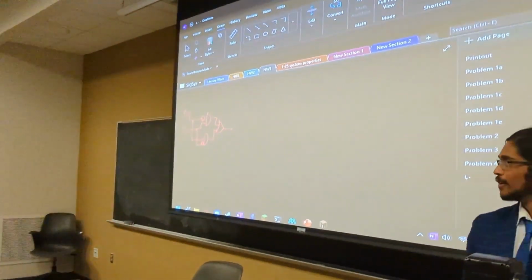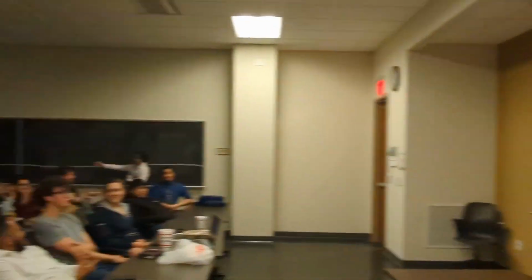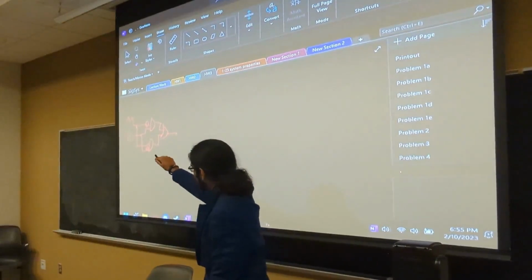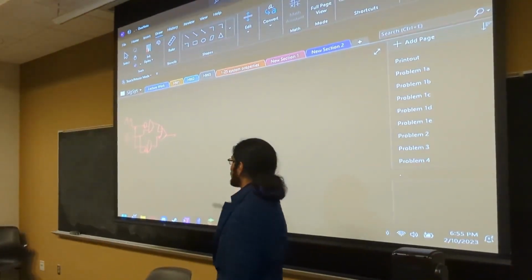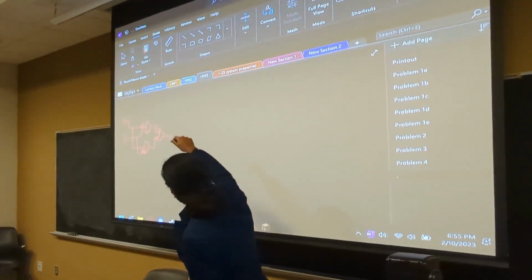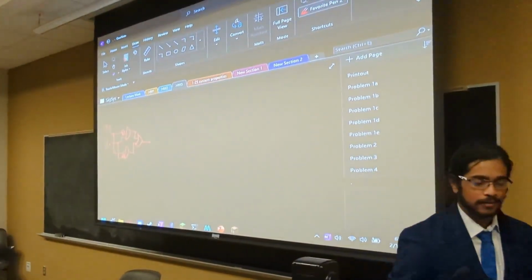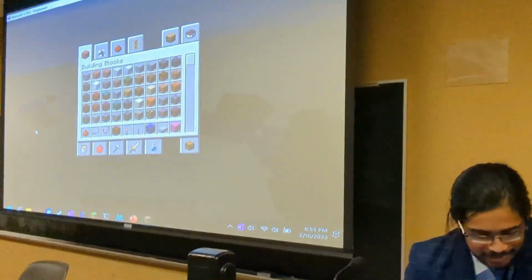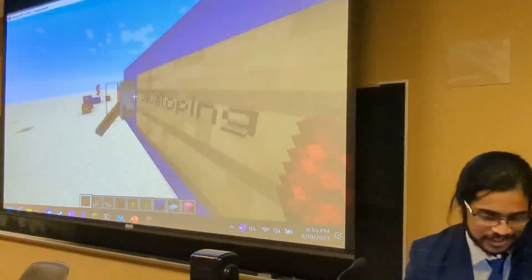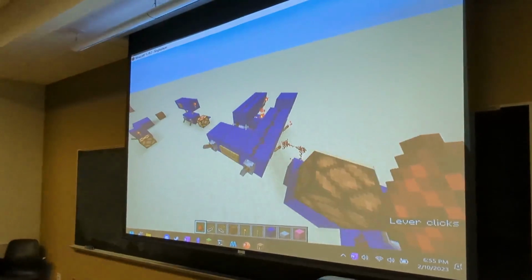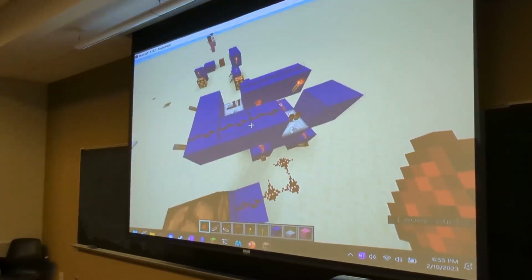Like that. So if we create this circuit here, we'll have the inverse of A and the normal B coming together, or the inverse of B and normal A coming together. And if either of those two inputs are on, then we get an output of 1. And we can create that in Minecraft like this, which looks very complicated, it's huge, but